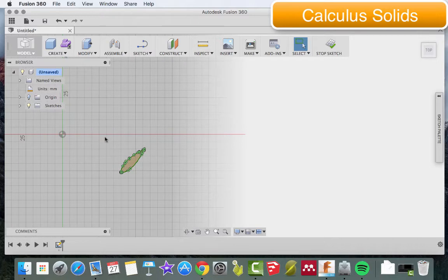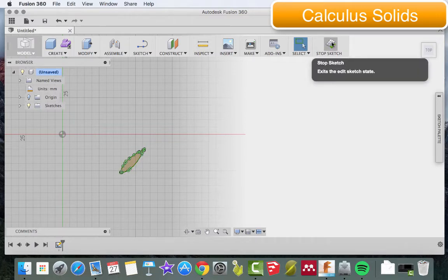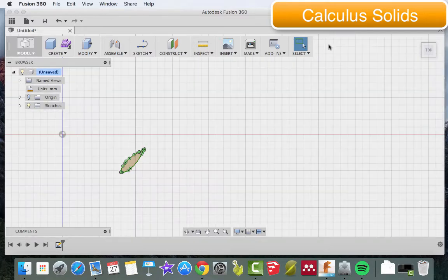And now we're talking. So I have something that is going to be about 25 millimeters, and I can choose to scale that up or down depending on what it is that I want to do with this. But for the sake of what we're doing right now, I scaled it way down, pretty small, easy for me to work with. And I've got all these points here. These are all changes of direction, different arcs, different lines that the sketch is recognizing. So once I'm done dropping this in, I'm going to go ahead and click on Stop Sketch, and now I can manipulate this.